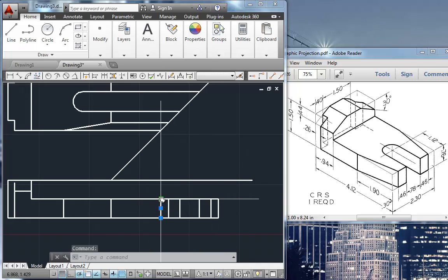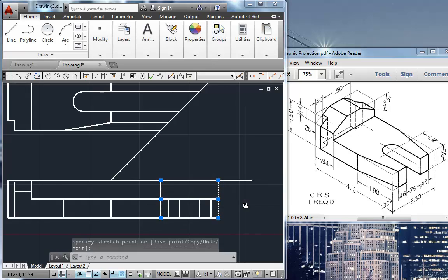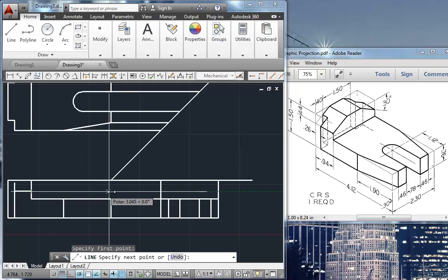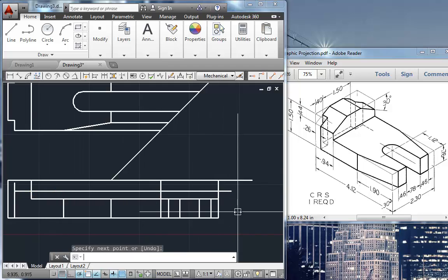This side's going to come up some distance. I don't really know how high yet. We'll take it up there. And now we have this angled surface, and how are we going to get that in there? It is a 30-degree drop from 0.44. So I'm going to take a line across from 0.44, and we're actually going to go uphill at 30 degrees.